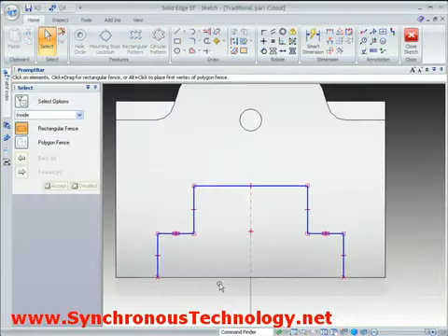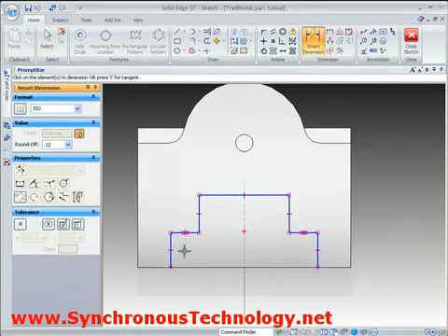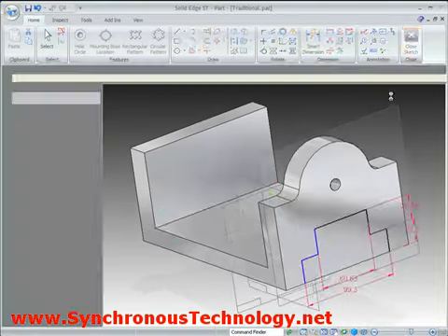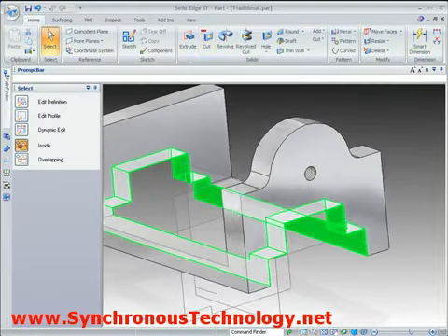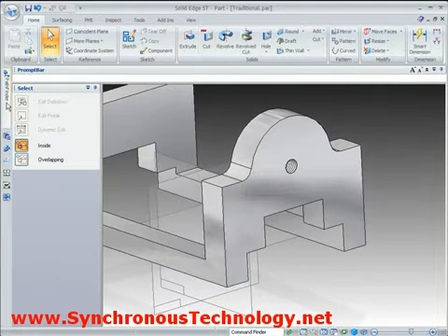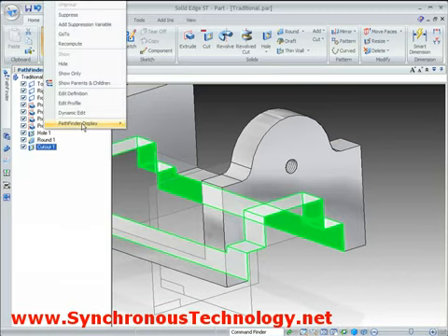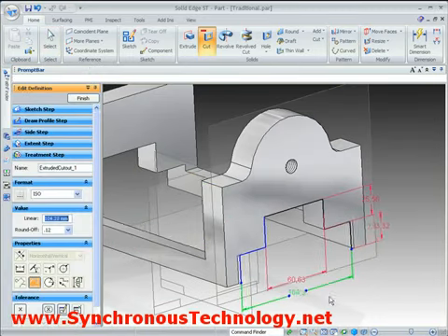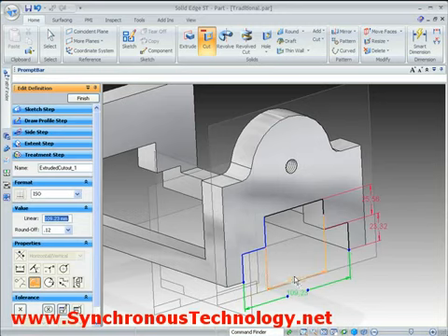Also, if we need to control any of the geometry with dimensions, these must be placed in the feature's profile or sketch, since it is the profile that ultimately controls the resulting solid model. Once again, these edits require the history of the model to be recomputed every time a dimensional value is changed.